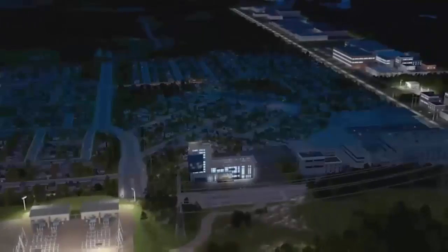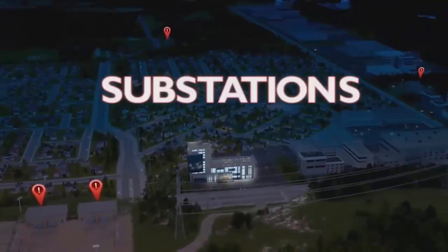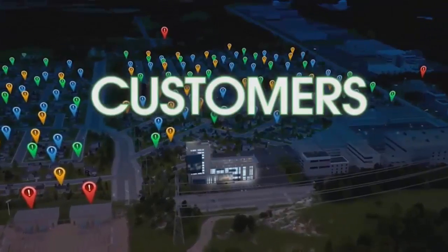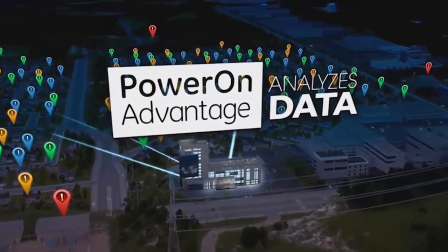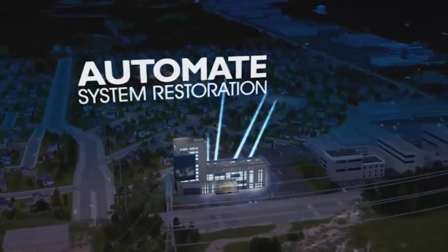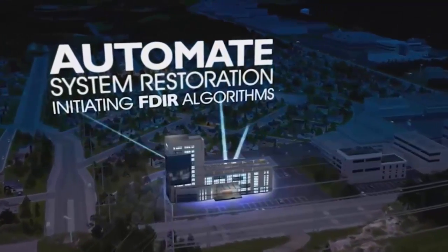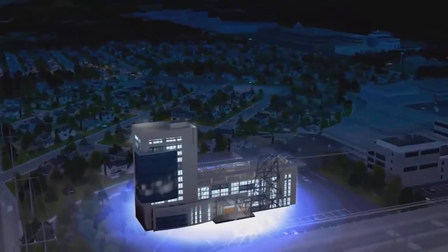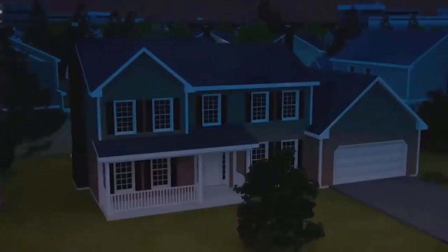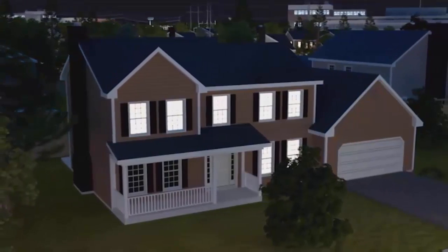When an outage starts, grid information from substations, circuits, meters, and customers is communicated to the control center. Power On Advantage analyzes this data and can automate system restoration by initiating FDIR algorithms and executing switching to isolate the problem section of the circuit, quickly restoring as many customers as possible.